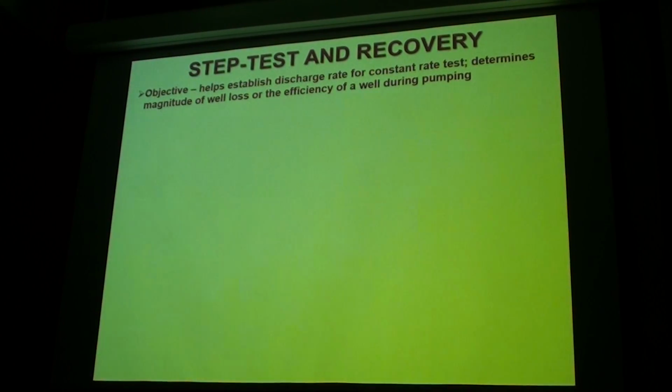So the first thing you should do, before pump testing, before you get into the nuts and bolts of the thing, is a step test: measure the water level at different pumping rates and then the recovery within the well. You can analyse that and it gives you an idea of how well your well's going to perform and what the maximum rate you may be able to pump it at during pumping testing, hopefully confirming the amount you want.